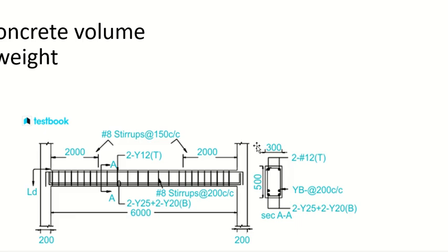So what extra should I add here? I'm missing something here. What am I missing? Because we consider the overlapping for the reinforcement, the end. The end, yes. Okay, so we need to add this thing. Now this thing, the one which you see going straight down, it is normally 6 times of dia. 6 times of dia, the thing which is going down.